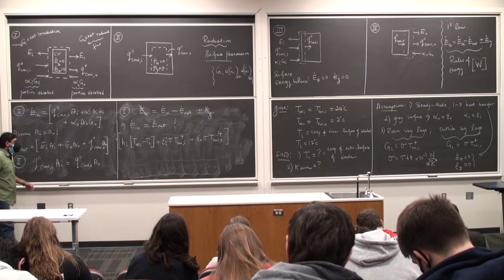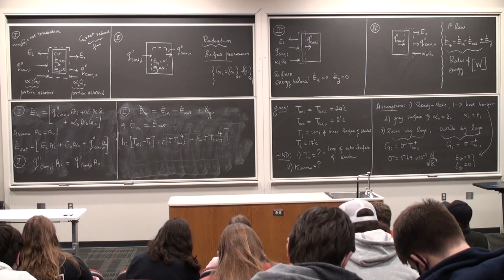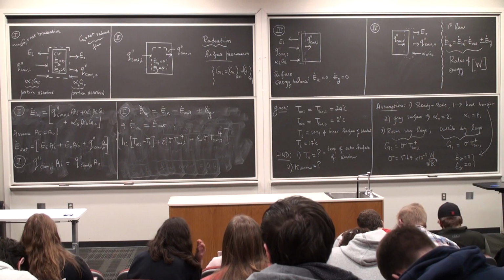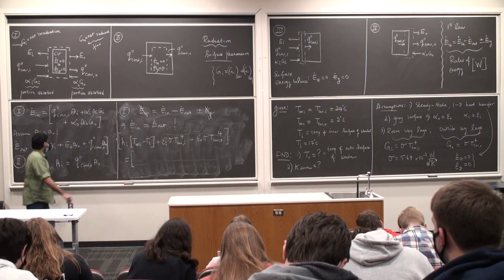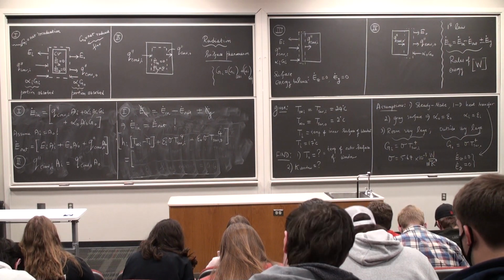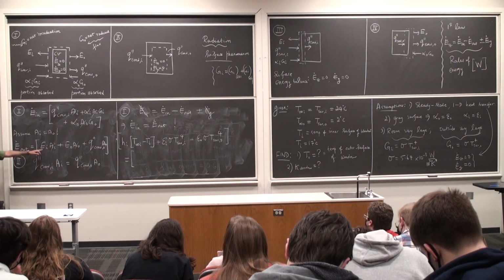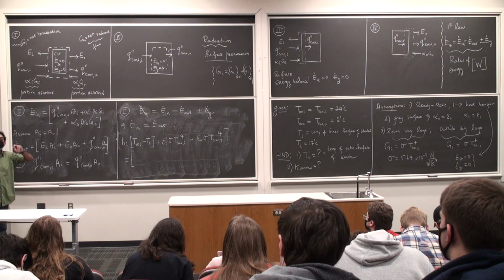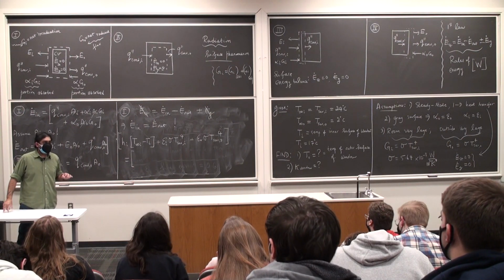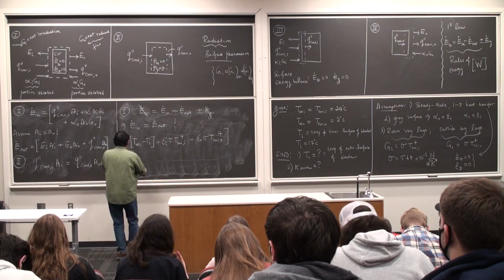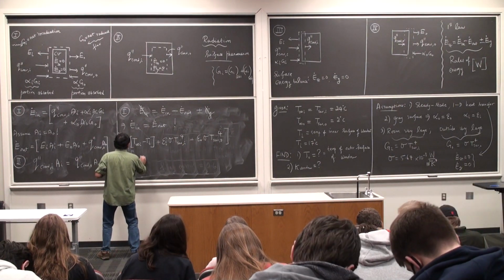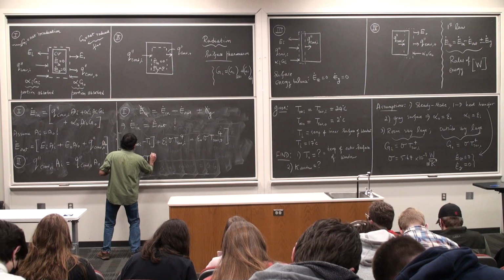These are all the terms coming in. Same treatment for terms going out. Emitted radiant flux is a fraction of the ideal emitter. And this is going to be epsilon times sigma times the temperature of the surface to the power 4. So this is epsilon I sigma Ti to the power 4.